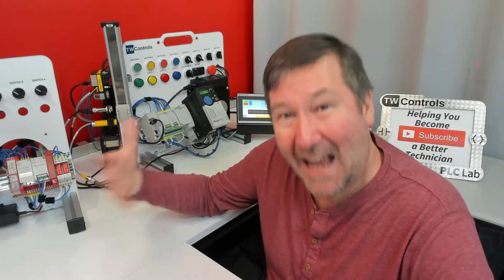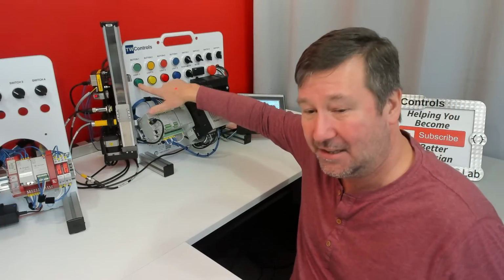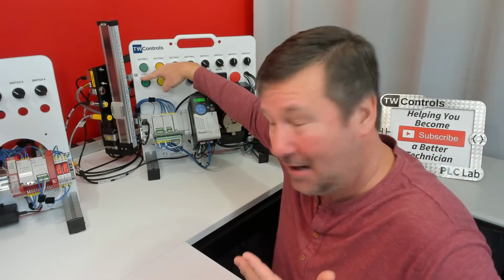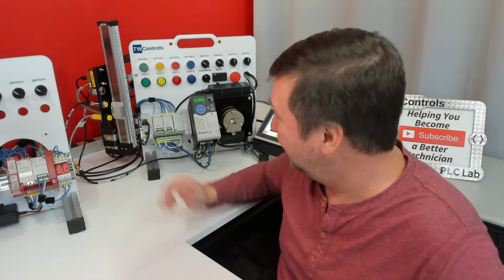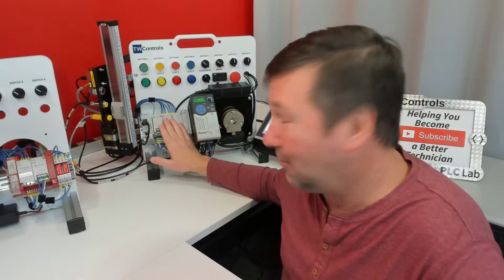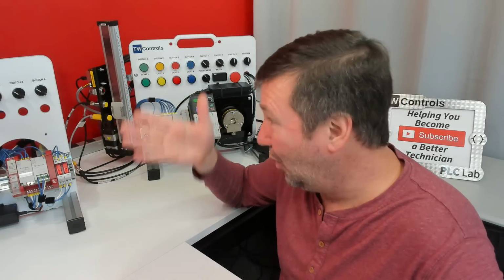What do we observe about the machine? Mainly, what's the action item it's not doing? Okay, I want this green light to light up right here. Where's the green light go to? It's going to be an output. We go find that. We figure out what its address is, and then we can work our way back into the program. And that whole video walks us through that, and then figure out what's missing.